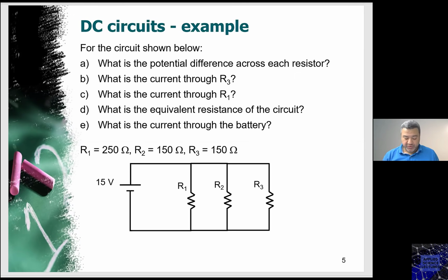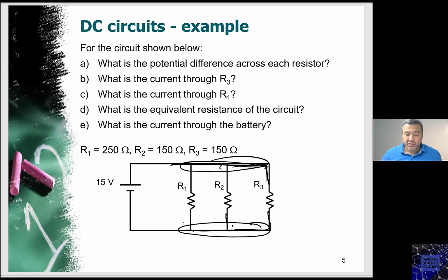Just by looking at those 3 resistors, I can say right away that those 3 resistors are in parallel. Why? Because they are sharing this node, such that R3 is connected from both sides, as you can see, with R2 and R1. No other components in between, so only with wires. In this case, I can call R1, R2 and R3 resistors connected in parallel.